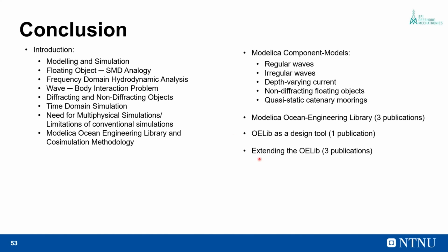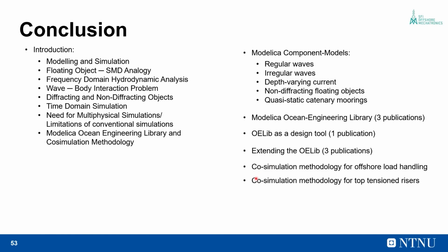We then talked about extending the capabilities of the Ocean Engineering Library by developing component models for mooring using the lumped mass approach, and by developing component models for diffracting floating objects, where we discussed the publication regarding OM-HYDE, the frequency domain hydrodynamic analysis software. We then talked about the cosimulation methodology for offshore load handling. And finally, we talked about the cosimulation methodology for top tension risers.